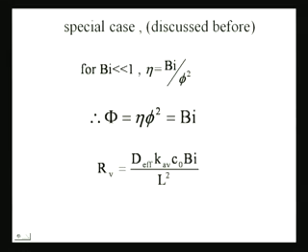And what you find over here is, look at this, very interesting, that it depends only on the external mass transfer. Why? Because Biot number already has a D effective, which will get cancelled with this D effective, and you will only be left with the external mass transfer coefficient. Is it clear? Right. So because Biot number itself has a D effective in it, 1 over D effective or something like that, which will get cancelled, and L squared will get cancelled.